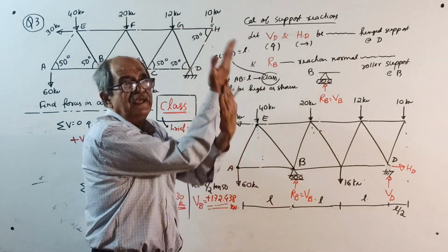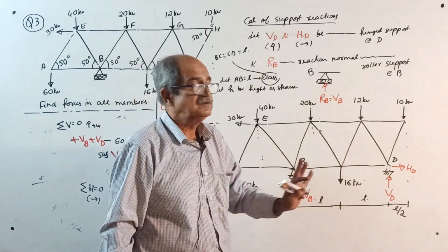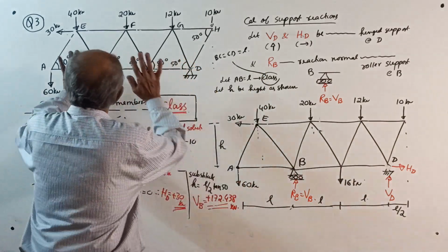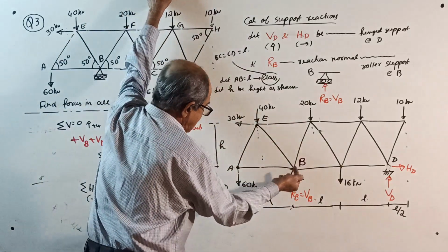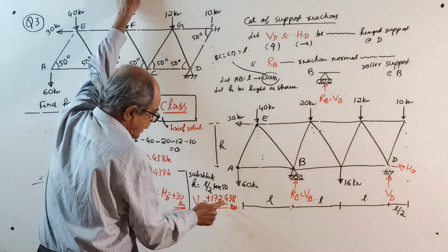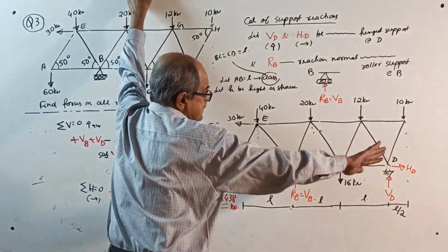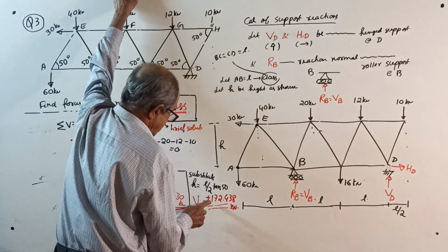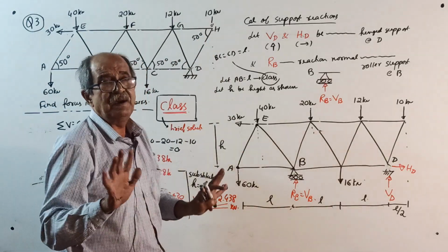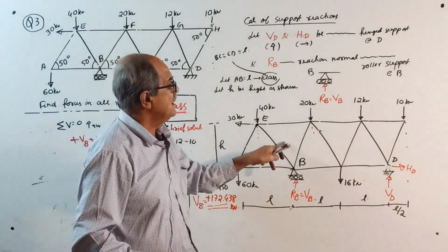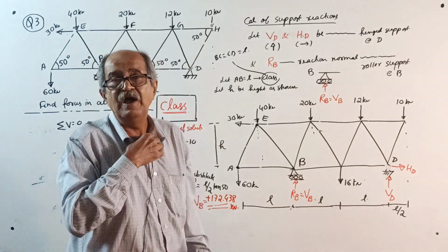So to prevent lifting up, vertical reaction will come down. I wanted a negative sign for the reaction. Okay, over. Now we will go to the star sketch. When I go to the star sketch, I already told you, VB I will enter 172.438 up. HD I will enter 30 kN right side. But VD I will enter 14.438 kN down. Remember that one. That's all. All inclined members are at 50 degree angle, the full board I can remove now. Okay. I will remove and make the entry.